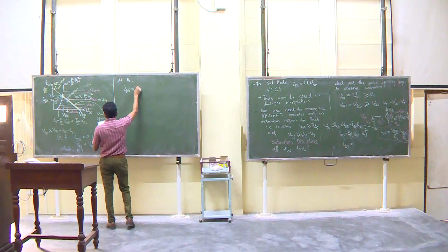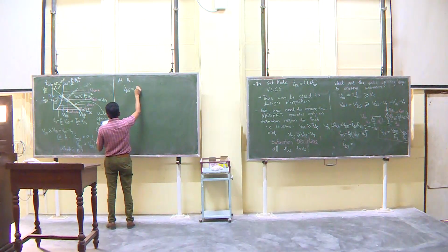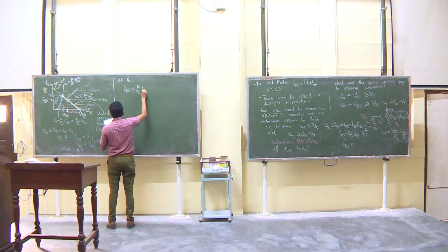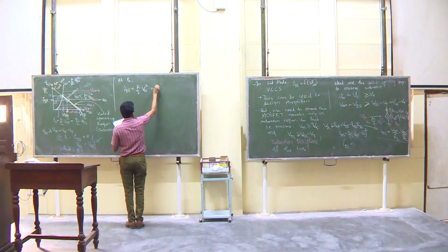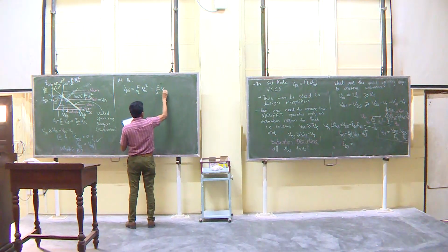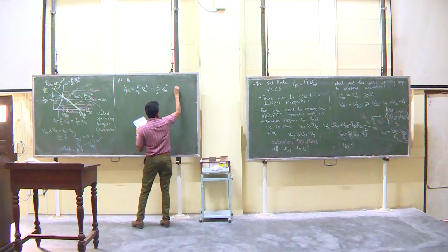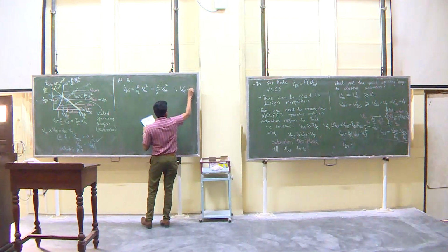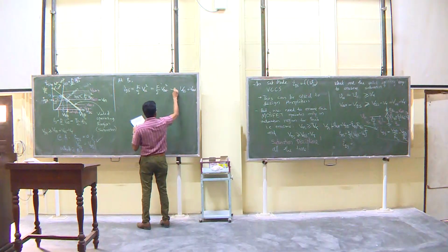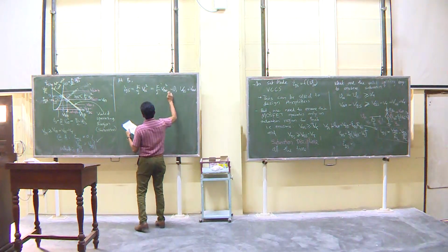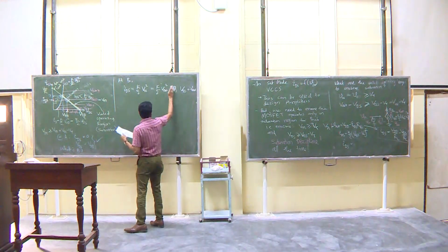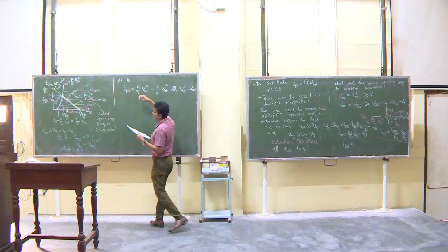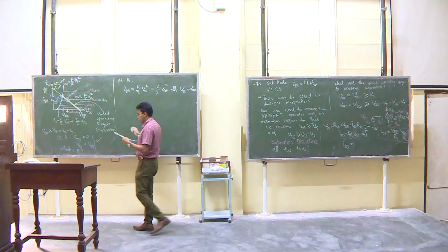It is equal to K divided by 2 VDS squared, which is equal to K divided by 2 V out squared, because VDS is equal to V out. Okay, so let me call this number 2. The numbers are different in my note and this, but it is okay.